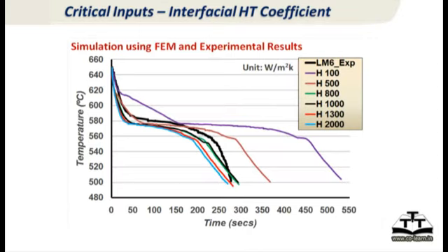So we did some experiments on this also. We took a popular high-end simulation package available in a research lab in India. We went there and we did 2 things. First thing we did is we actually made a real casting. So the black line here in the middle, you can see this black line, that is a result from a thermocouple in the mold. So that is the truth. The black line is the truth because we measured it from a thermocouple in the mold.